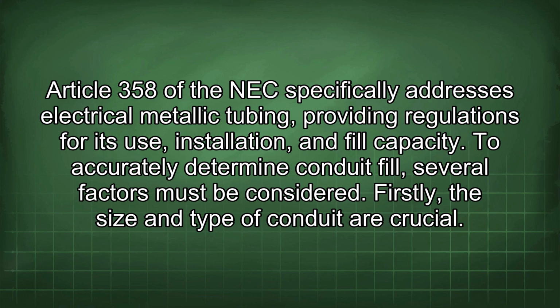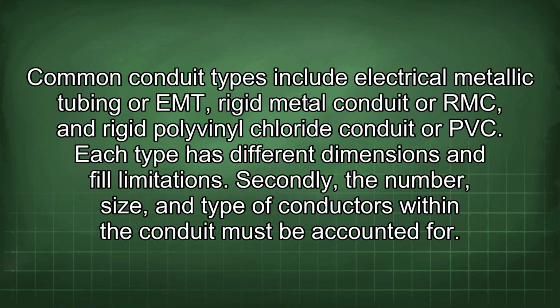To accurately determine conduit fill, several factors must be considered. Firstly, the size and type of conduit are crucial. Common conduit types include electrical metallic tubing, or EMT, rigid metal conduit, or RMC, and rigid polyvinyl chloride conduit, or PVC. Each type has different dimensions and fill limitations.